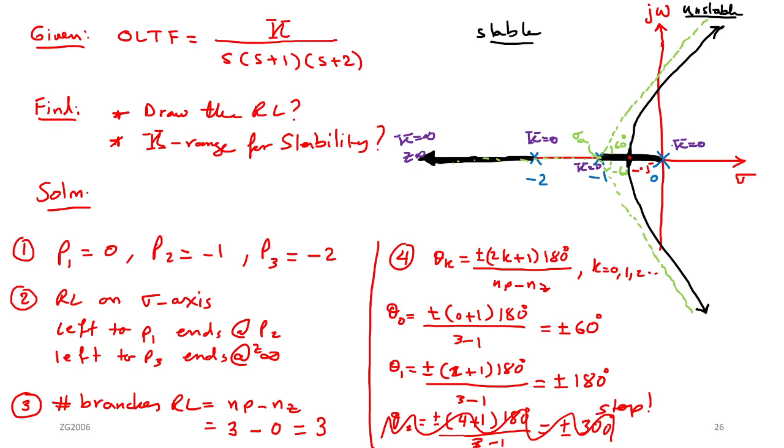We will call it 0 at infinity. Okay. What about this root when k equal to infinity? When k equal to infinity, it will go to another 0 at infinity. We call it 0 at infinity. This one, same thing. When k equal to infinity, it will go to another 0 at infinity. So we will imagine there is a 0 far away there. In other words, what if we have a real 0 here? Like at -3, we have a 0, -3. What will happen to this root locus? It will stop here when k equal to infinity. You got it? I hope this is clear.